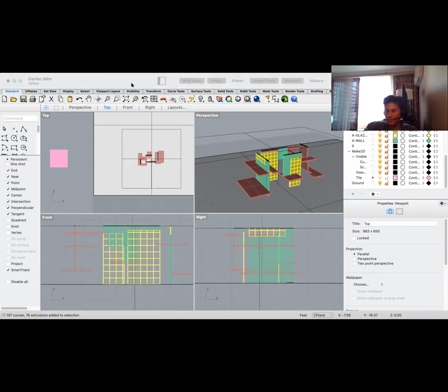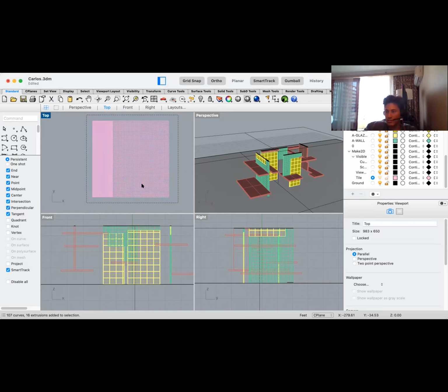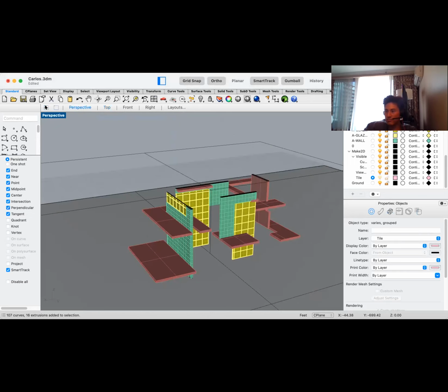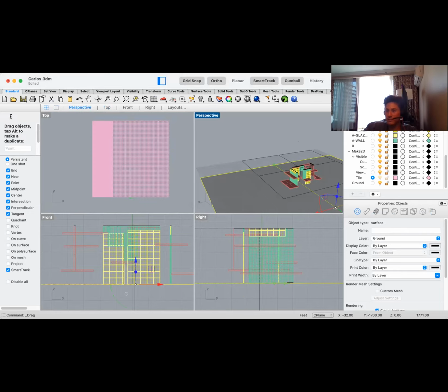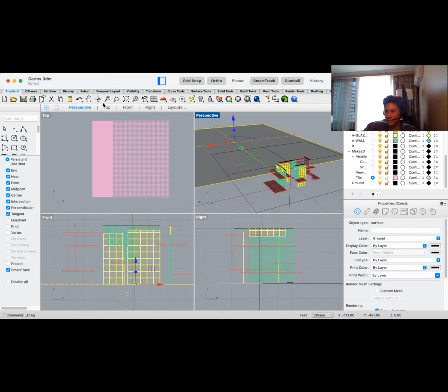Okay, well, let's zoom in on that tile. So highlight your tile in top view. Okay, and then come into your perspective, click on your perspective tab at the top, and then type ZS. Oh, you want to see all four? Yeah, see all four. So just type ZS, enter. Don't deselect anything. I think you typed something wrong. It's fine. Just escape. Let's highlight your tile in your top view.